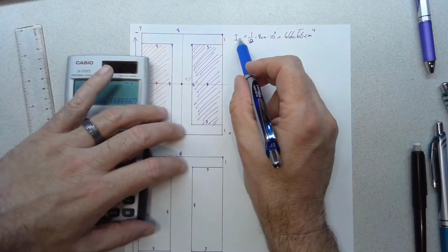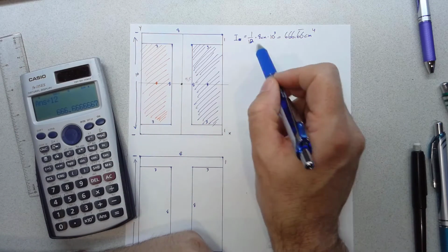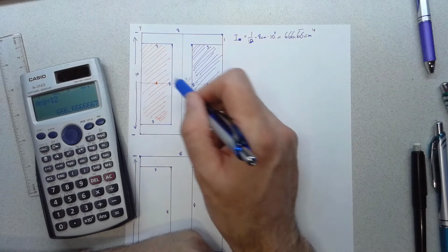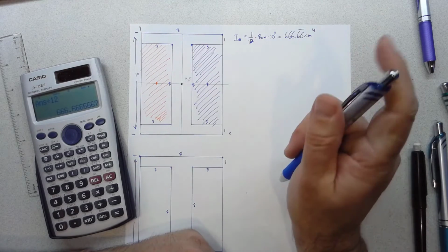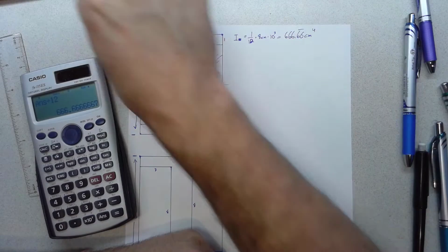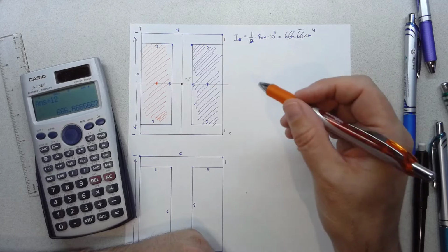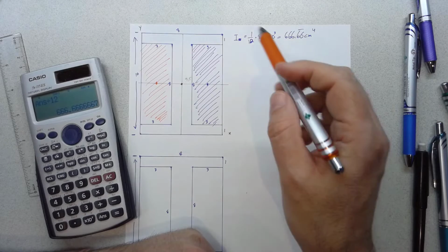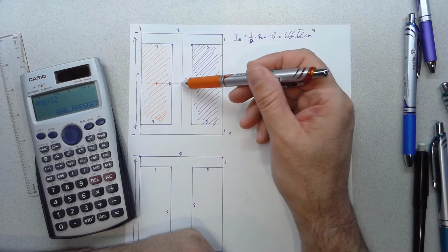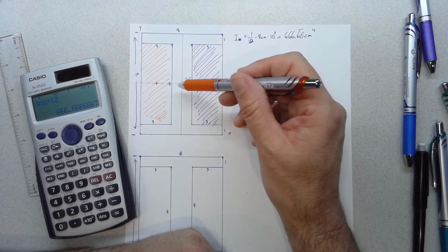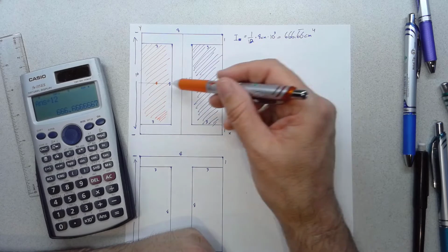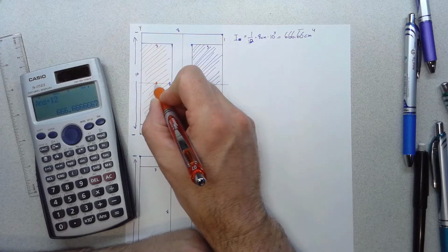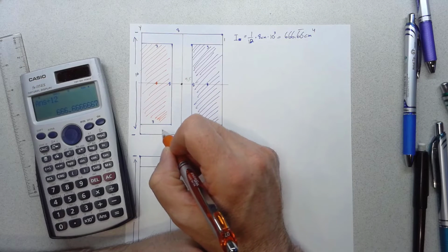Okay, so we found I for the big rectangle about the big rectangle's neutral axis, which happens to be the neutral axis of our composite shape as well, so we don't have to use the parallel axis theorem. I'm going to keep harping on that because this is one of the few instances where we don't need to. Let's reiterate: you don't need to use the parallel axis theorem if the centroid of the component piece you're looking at is along the line of the centroid of the final shape as well. So let's look at the I about this axis, which runs through its centroid. Again, we won't need the parallel axis theorem.